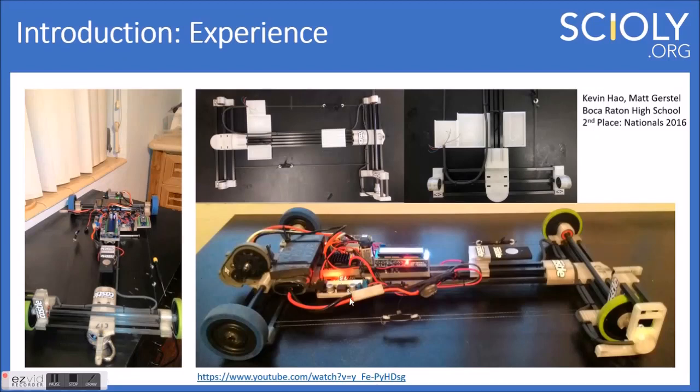We have a voltage regulator that you can see down here, and that was just feeding the motor a consistent voltage, as well as powering any other electronics that we needed at a certain voltage. I don't remember exactly what we were using it for. I think the motor was run purely off the 7.2 nickel metal hydride battery that we have under this steel block over here. And I think this voltage regulator was to ensure that when the voltage dropped, because the motor was pulling so much current, the electronics on board wouldn't turn off. So it boosted up the voltage if it was dropping, so that the Arduinos were getting fed a constant voltage, which was very important to make sure they did not just turn on and off. We did have that problem a little bit.